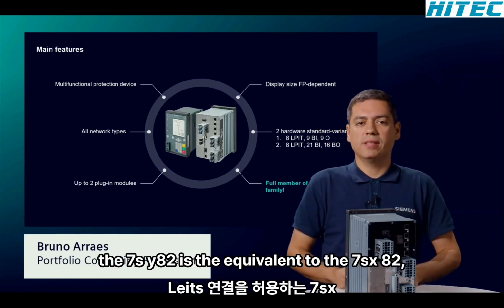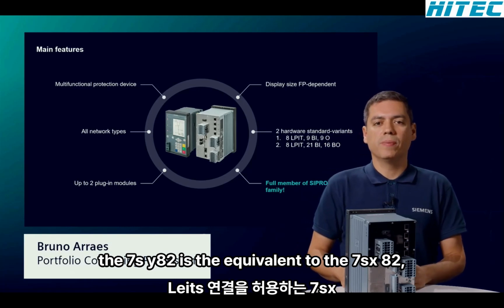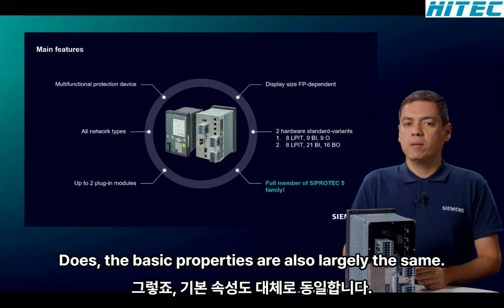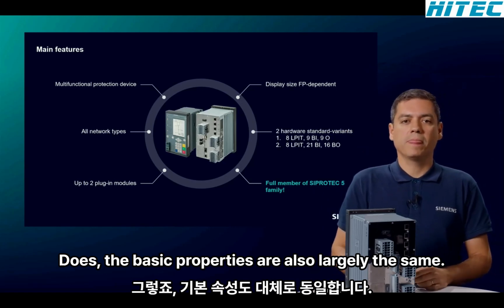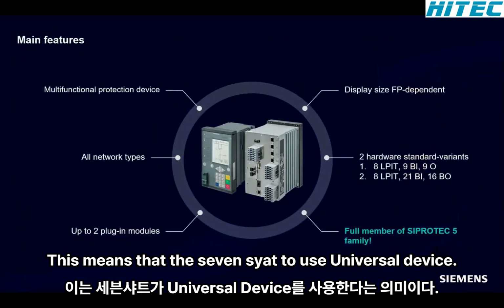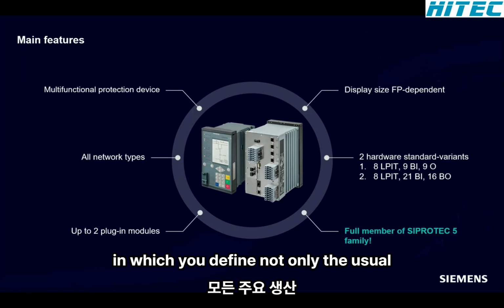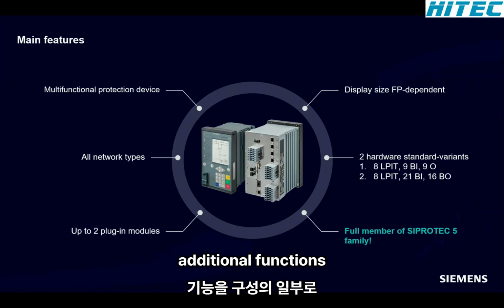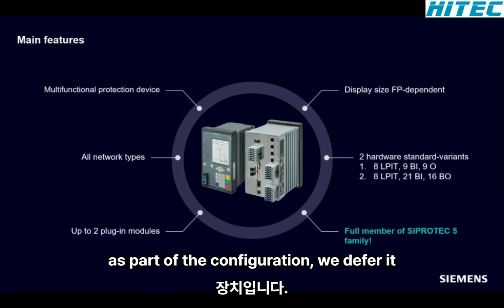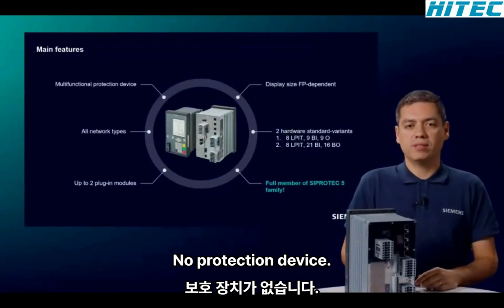As we have just heard, the 7SY82 is the equivalent to the 7SX82, which allows the connections of LPITs. Thus, the basic properties are also largely the same. This means that the 7SY82 is a universal device. In other words, a digital protection device in which you define not only the usual additional functions, but also all the main protection function as part of the configuration. We therefore speak of a multifunctional protection device.